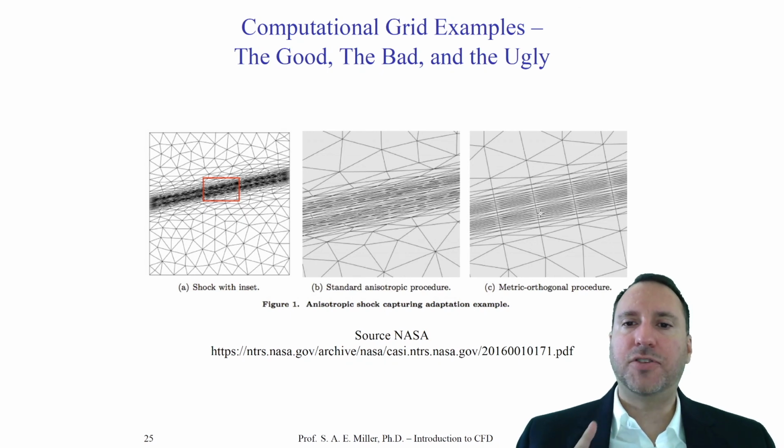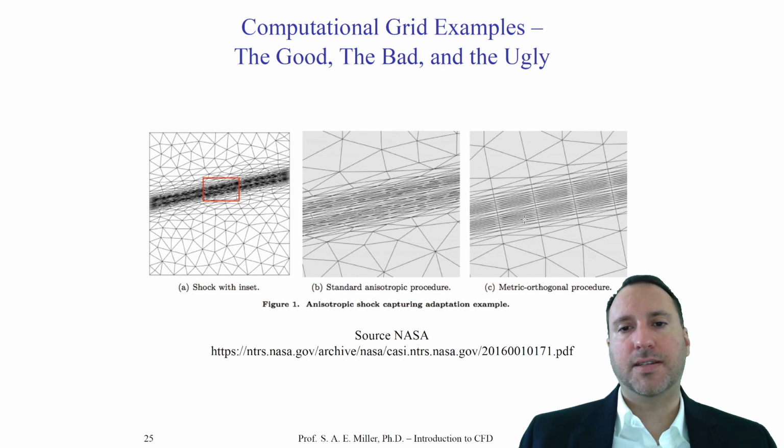The difference is they've structured the triangles within the shockwave region, and that's the best they can do with this type of solver. The only thing they could do better perhaps is add more grid lines in the direction that I'm moving my cursor to reduce the skewness angle, but that would greatly increase computational power, and their solver is robust enough to handle these small angles.